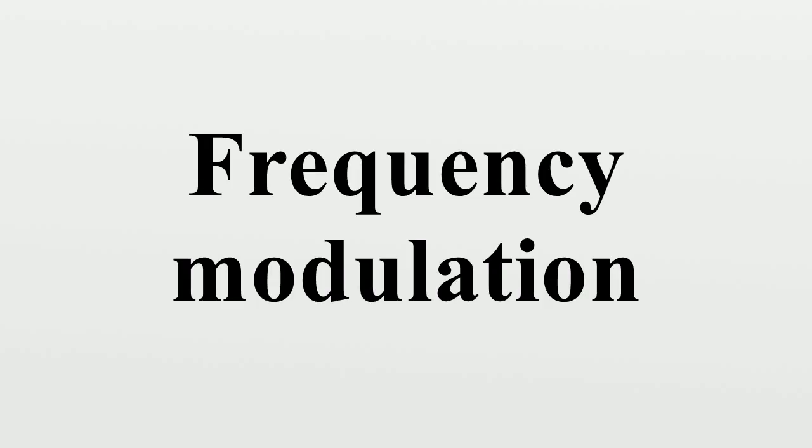For example, 3 kHz deviation modulated by a 2.2 kHz audio tone produces a modulation index of 1.36. Suppose that we limit ourselves to only those sidebands that have a relative amplitude of at least 0.01. Then, examining the chart shows this modulation index will produce 3 sidebands. These 3 sidebands, when doubled, gives us 6 times 2.2 kHz, or 13.2 kHz required bandwidth.